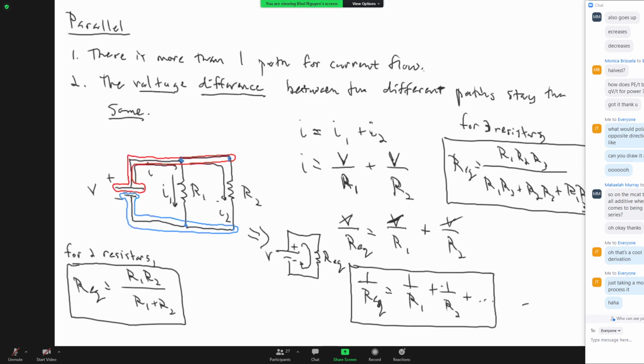This is meant to be an arrow. I just use this equation. Sometimes it's just easier to do though, if they're all the same resistors, like 1/2 or 1/3, 1/3, 1/3, and take the reciprocal, that's just 3 over 3. And your equivalent resistance would have been, right? If you have 3 ohm resistors in a row in parallel, then they are equivalent to 1 ohm resistor.